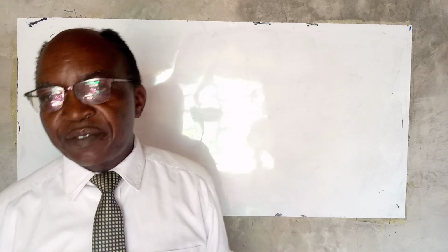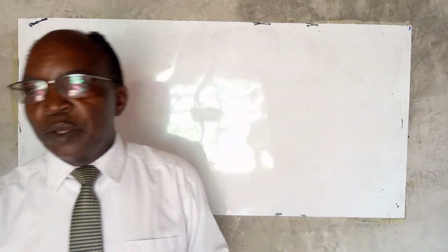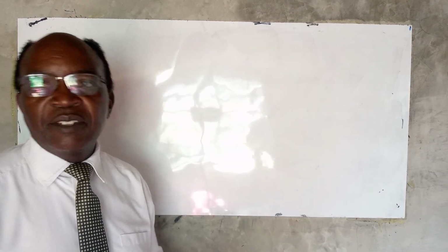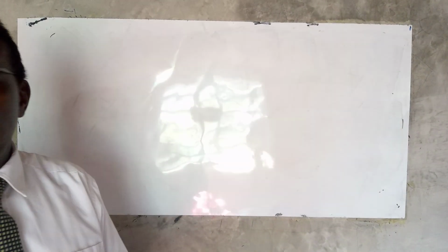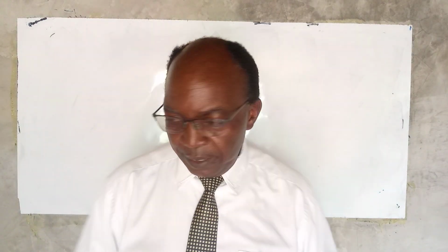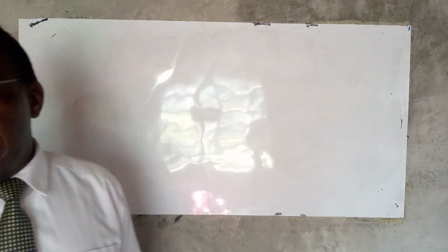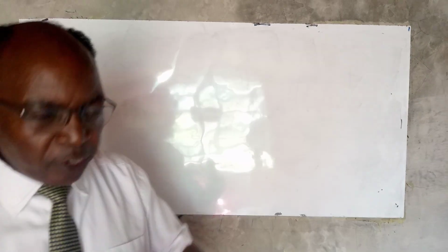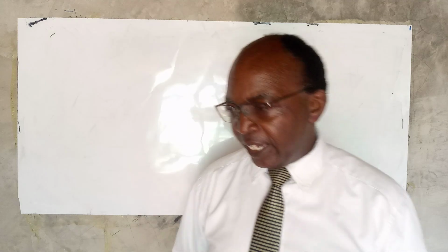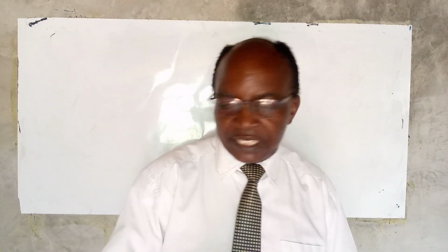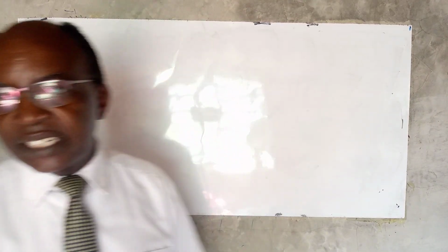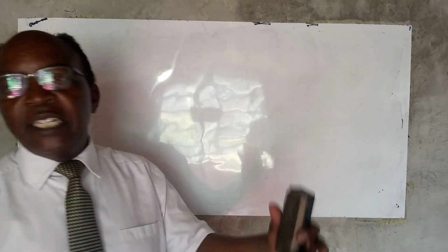Today we want to look at heat transfer in a cooling fin. So let us say that we have heat being transferred between a liquid and a metal surface. In that case, normally most of the resistance will be in the fluid boundary with that wall. So what do we normally do? You can have fins, and the whole idea about fins is that it increases the surface area. And if there's an increase in surface area, there's significant efficiency in terms of heat transfer.